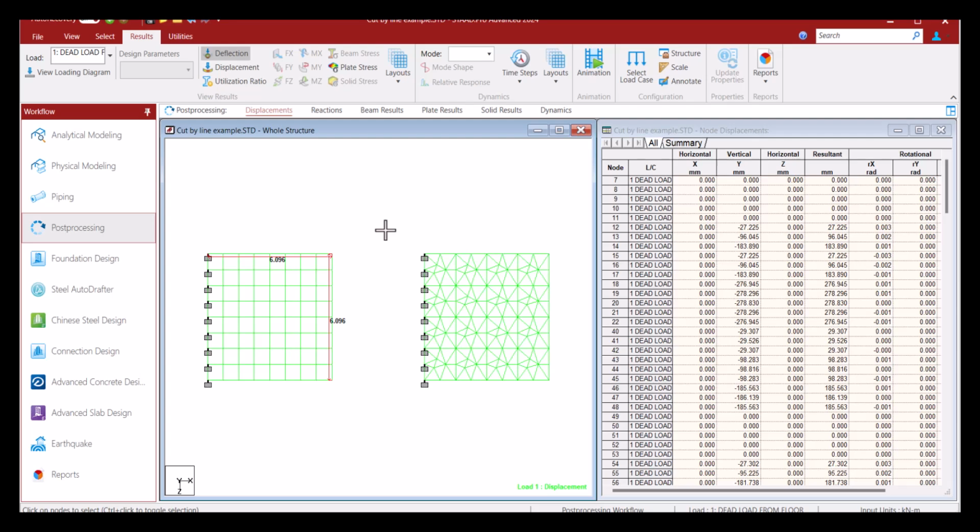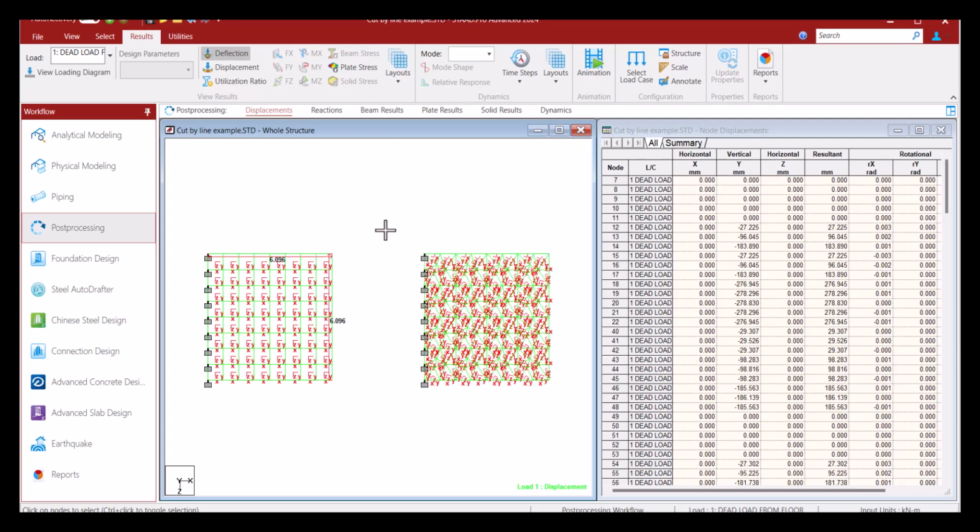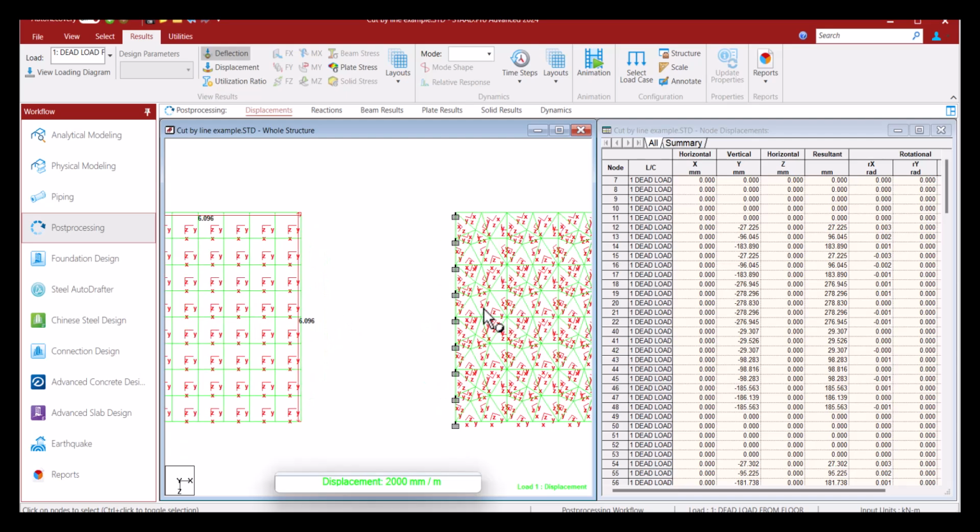If you hit Shift T, T as in Tom, you can see small individual axis systems appearing. Now these axis systems are essentially the local axis systems. Here you can see in this square pattern, all the local axis systems are very well oriented, in a proper direction. They have some unidirection. So yes, they are well organized. But on the other hand, if I zoom in here, you can see these are almost haphazard, and some of them are oriented in another direction.